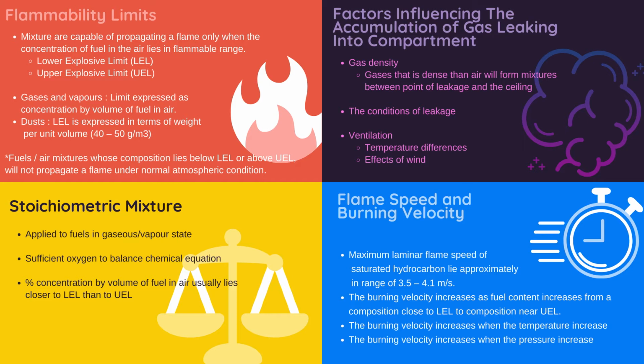Stoichiometric mixture is applied to fuel that is in gas or vapor state. This happens when sufficient oxygen is used to balance the process of hydrocarbon fuel converted into carbon dioxide and water. For stoichiometric mixture, percent concentration by volume of fuel in air usually lies closer to LEL than to UEL.